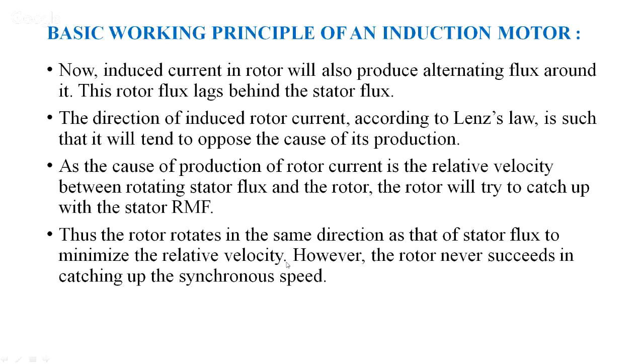The rotor starts rotating in the same direction as the stator flux, and it tries to catch up with it. However, the rotor never succeeds in catching up with the synchronous speed.